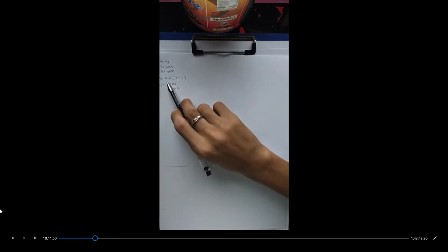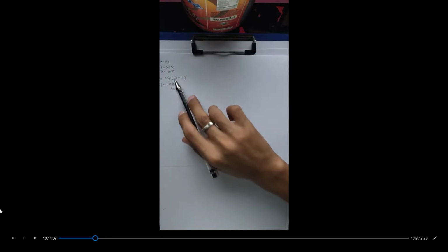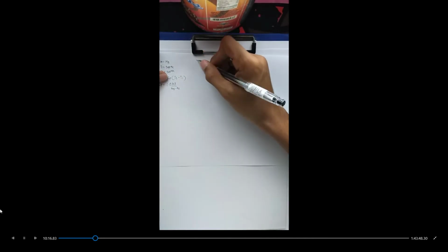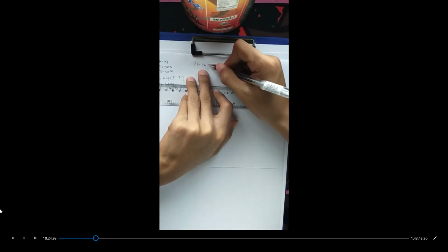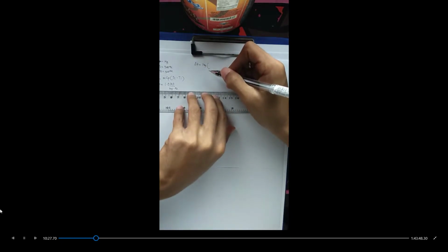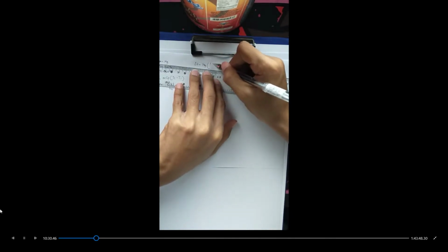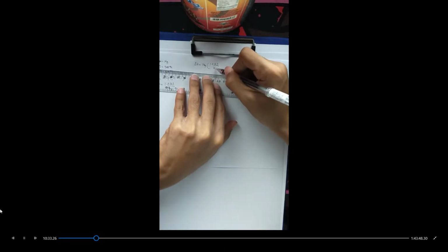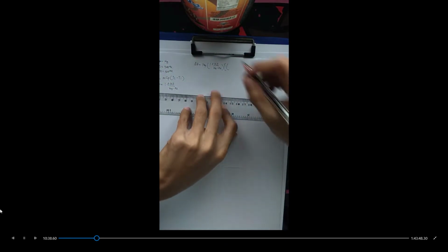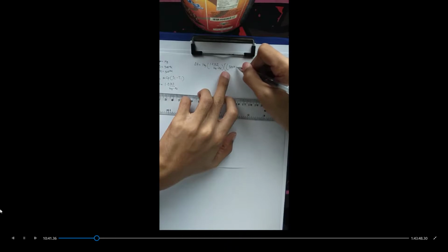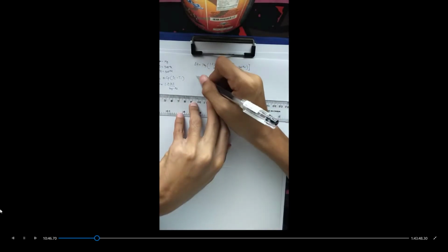By substituting all the values, we already have our mass, constant pressure specific heat, temperature 2 and temperature 1. All we have to do is substitute the values to our equation. So we have 1 kilogram multiplied by our constant pressure specific heat, which is 1.0 kilojoules per kilogram degree Kelvin, and then multiplying it by the change in our temperature, which is temperature 2, 500 degree Kelvin, minus temperature 1, 300 degree Kelvin, and we can now solve for our change in enthalpy.